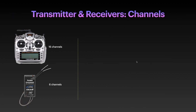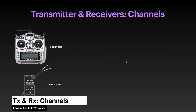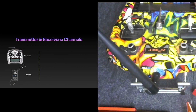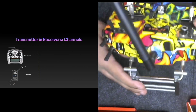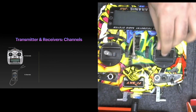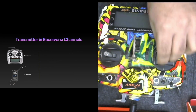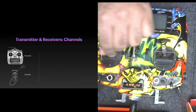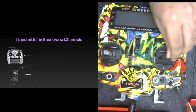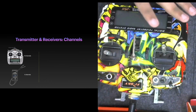So moving on, let's talk about the number of channels. Every transmitter has some channels, every receiver has some channels. This transmitter which I have has 16 channels, and let me move to the overhead camera to show you what the different channels are. This one has one channel for throttle, one channel for roll, one channel for pitch, one channel for yaw. So these are 4 channels.